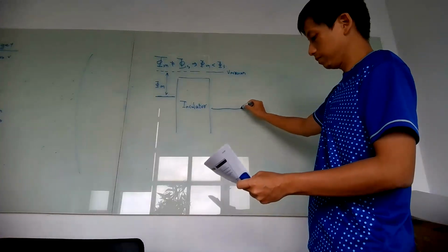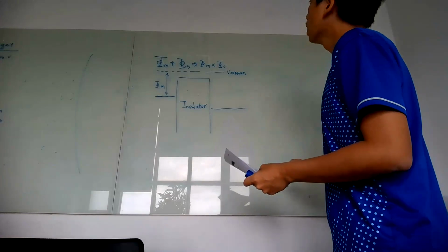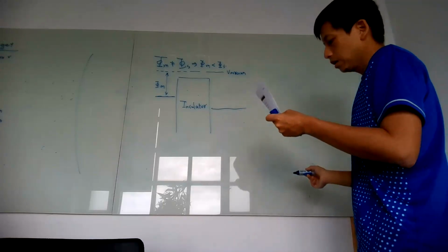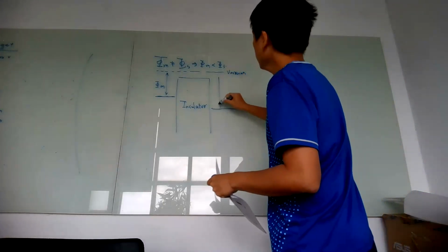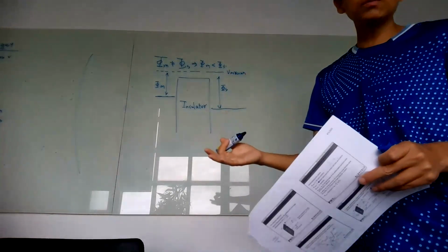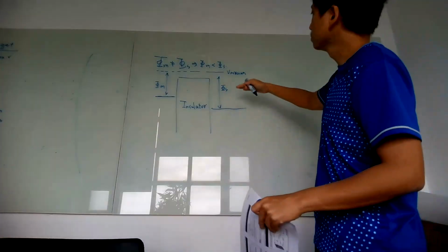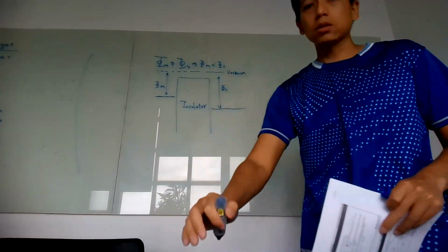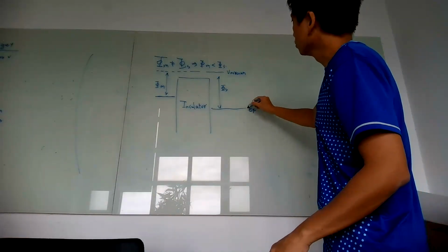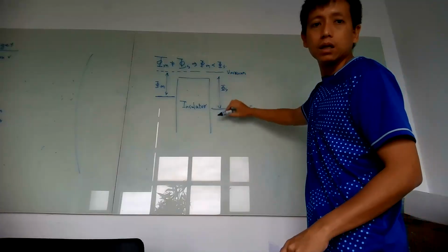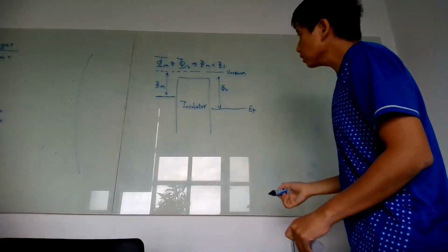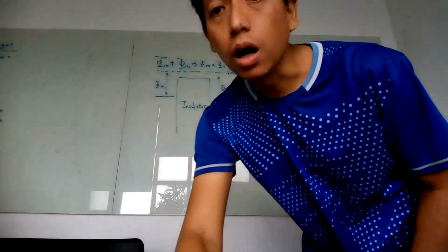And then after the insulator, we get the semiconductor, and for the semiconductor we get the work function, which you can see from the definition. It is the Fermi level to the vacuum level, right? If you go back to our previous slide, here's the Fermi level. From the Fermi level to the vacuum level, we get the work function. This one is larger than that in the metal.